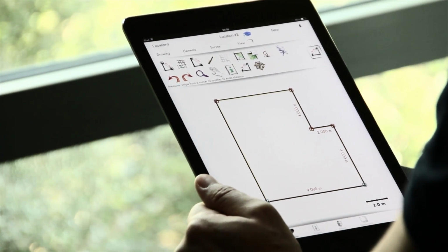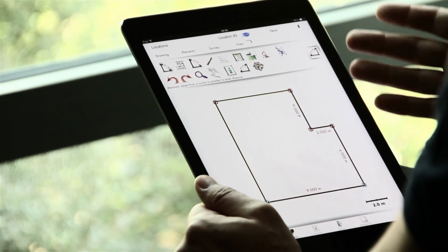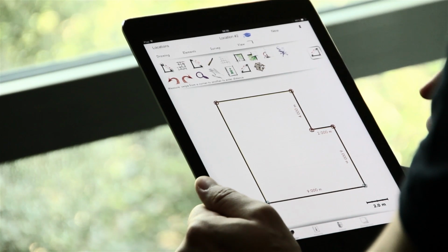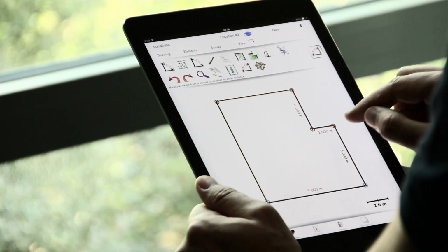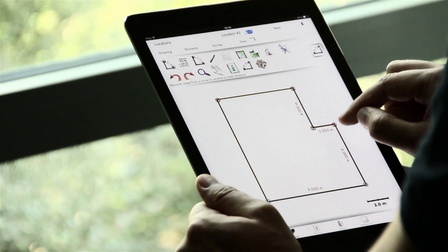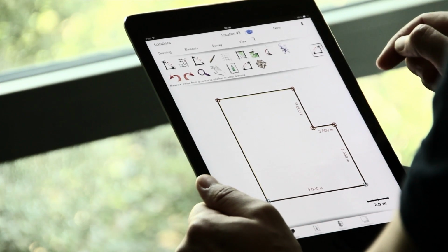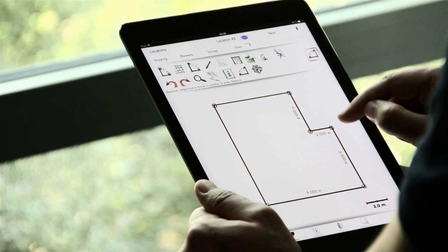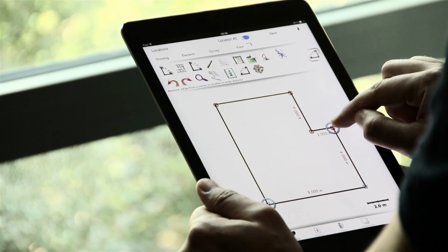So what we can see is that we have these circles here, and in order to turn them green, in order to turn them fixed, I have to have at least 2 measurements in that direction, because now I have only 1 to those red circles. I can do diagonal measurements in order to update those corners, and that's what I'm going to do now. Click on measure, and I'm going to measure from one point to one of the red circles, like that one.